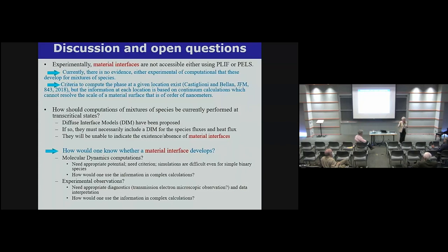You have to go beyond that, because mixing is a controlling thing. So the Batchelor scale and the thermal scales are smaller than that, okay? So dissipation, if you stopped at the Kolmogorov scale, you wouldn't get all the dissipation. These are direct numerical simulations, right? So you have to go beyond that in order to get the correct thing. It's not only compressibility, it's the fact that you get mixing. There are many reasons why the Kolmogorov scale is not here necessarily the relevant scale. Okay? I hope I answered your question.